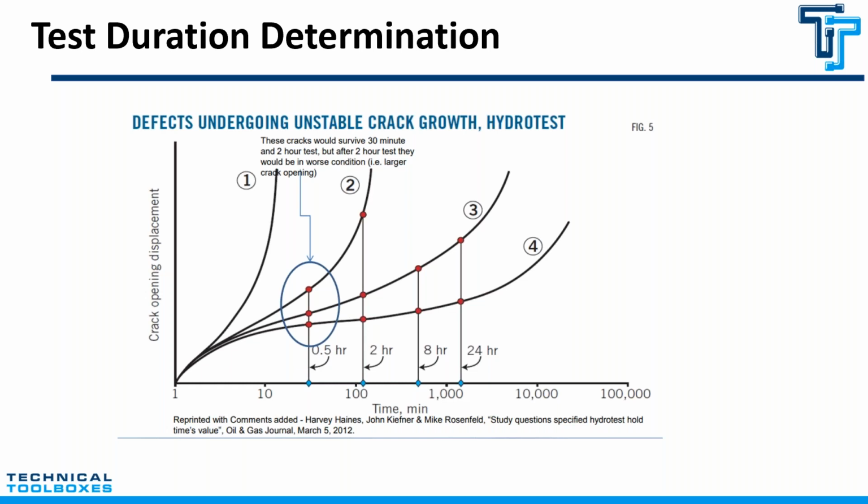Thanks, Joe. And one last question here. Any recommended diameters where hydrotest is not recommended? I think a way to look at that is that what we have presented from a hydrotesting standpoint is for the transmission lines. For distribution lines, where the pressure difference is significantly lower and the length of the pipe is lower, you don't necessarily have to do hydrotest.